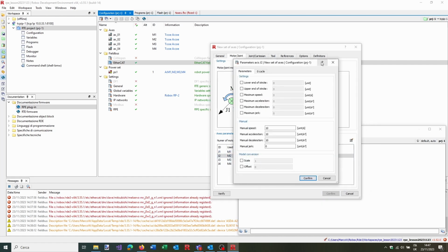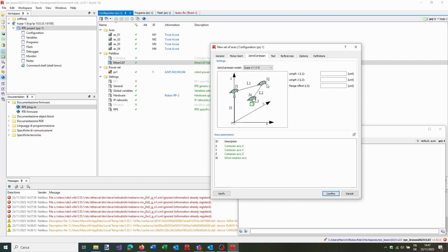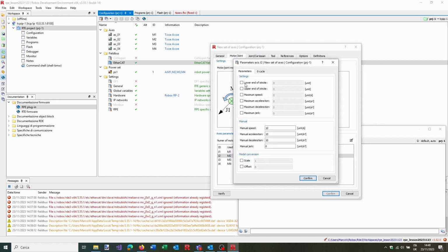Now let's go to number 2, that, as we see here, is the axis of the elbow. Here again, let's just make easy things. In this case, I'd like to go from minus 150 to plus 150 degrees. I'd like again 1000, acceleration 1g 981, and jerk again 420,000.